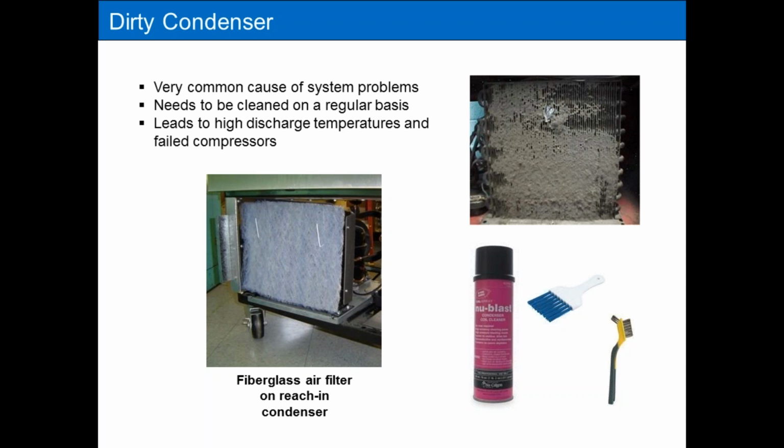So you got to see what type of dirt you're dealing with. Is it grease, hardened grease? That's problematic. Or if it's just something that could be brushed off. Now, when you're dealing with just dirt, like I'm showing you on the screen, word of caution, don't blow it out with compressed air or nitrogen. Compressed air or nitrogen will clean those condensers really well.